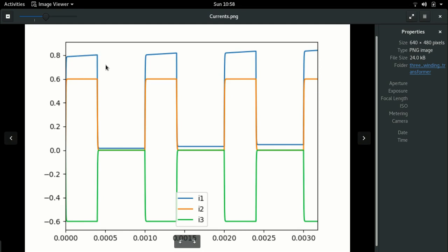since it is a step down transformer, we expect the high voltage winding to have lower current. So actually speaking, the current in this primary winding, sorry, high voltage winding, should be half of that of winding 2 and winding 3. But what is important to understand is winding 1 is supplying the current in both winding 2 and in winding 3. And it is also supplying this magnetizing current. So this is the reason why you will see that this current in the winding 1 appears to be more.